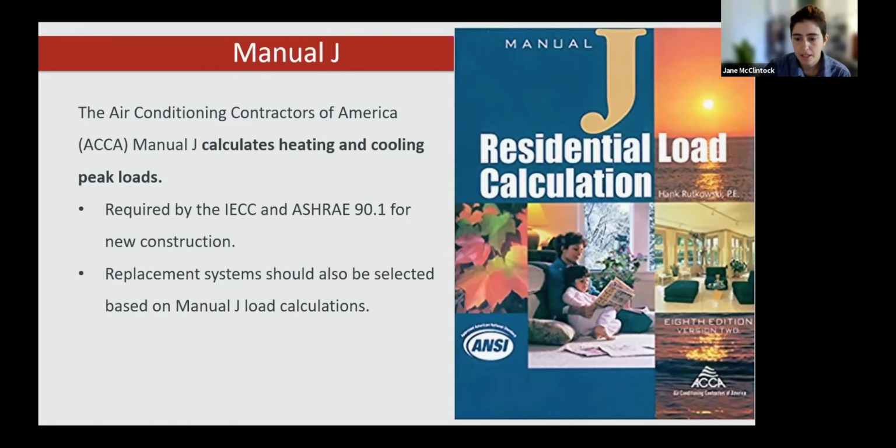And it's a requirement of the Energy Code because it's critical to appropriately size HVAC units, both for their efficient operation and to provide dehumidification, because oversized units are going to short cycle, reducing efficiency, and also often not running long enough to effectively dehumidify spaces. They also lead to increased comfort and proper operation of those systems. Proper sizing, as an added bonus, also avoids excessive upfront capital costs related to oversizing equipment when it's not needed.